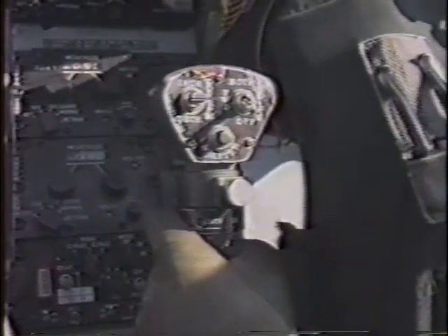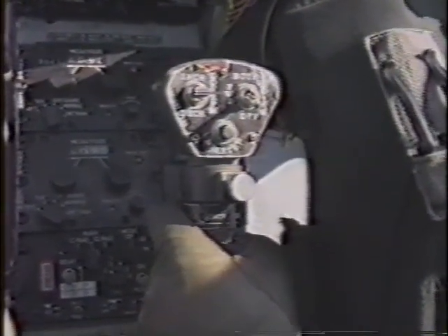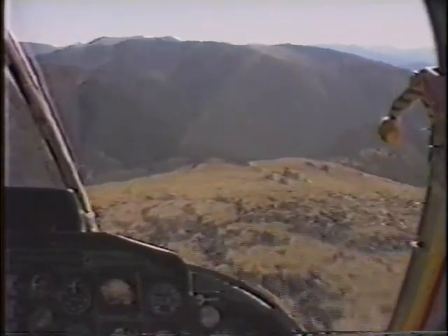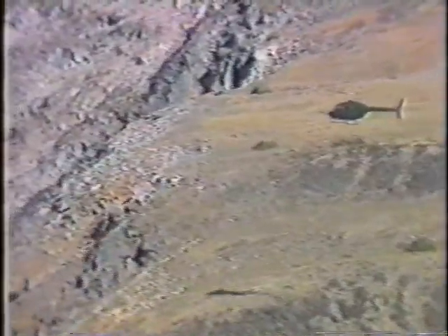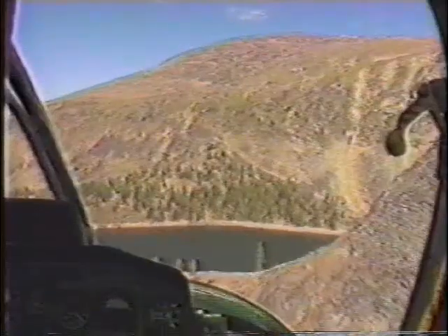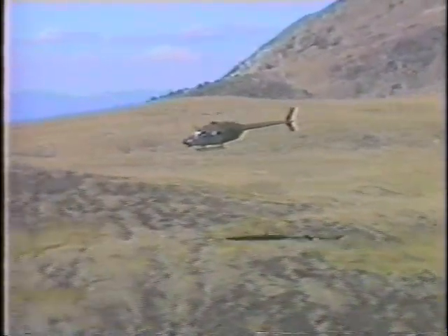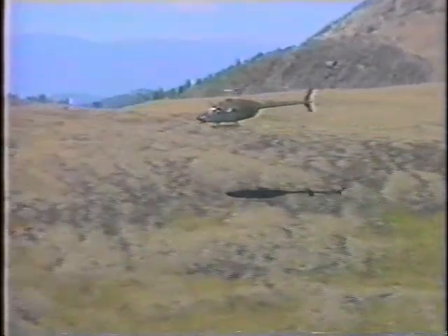A couple of other points about the takeoff. Make sure you've got enough collective to complete the takeoff you've chosen, and check your cyclic for load distribution or other problems on the initial hover. Discovering an abnormal response later may be too late. A basic understanding of the terrain and topography will not only help you to predict the wind factors you'll have to deal with, but will also give you a head start in successfully completing your mountain operation, no matter what that operation may demand of you and your machine.